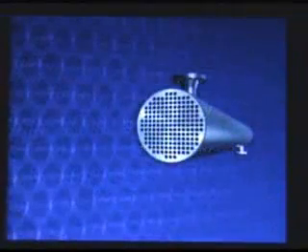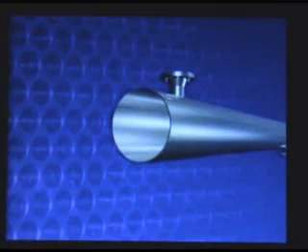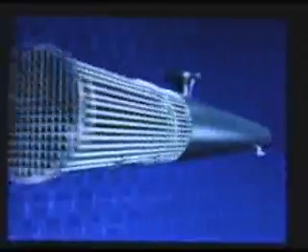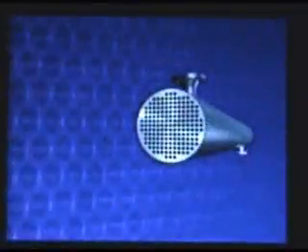Where with segmental baffles the shell side fluid has zones with various speeds causing inefficient heat transfer, the Helixchanger has an equal flow through almost the entire shell, leaving no space unused for heat transfer and therefore having outstanding heat transfer rates. The Helixchanger is extremely suitable to replace segmental baffled bundles in existing shell and tube arrangements. One simply pulls the conventional tube bundles out and inserts helical baffled bundles with all the helical advantages, and this increases the capacity by up to 20%.